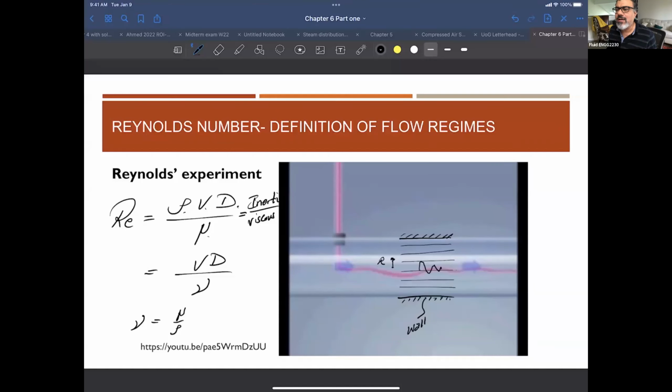Laminar? Evenly distributed. If the particles move up and down and mix with other particles, do you think the velocity will be more combined together, the smaller velocity mixed with the higher velocity? So turbulent is mixing more. Mixing means the velocity distribution inside the pipe will be a little bit more flat, almost the same. I'm going to explain this a little bit more as we get into the slide.